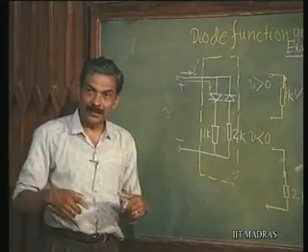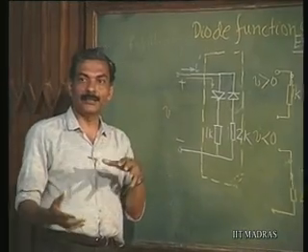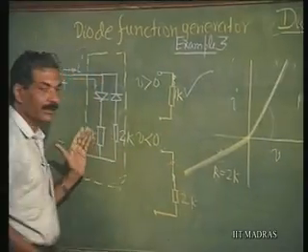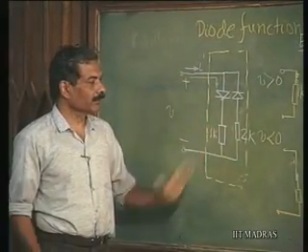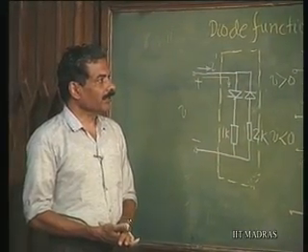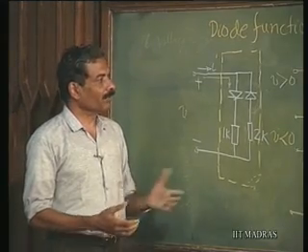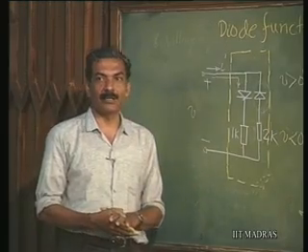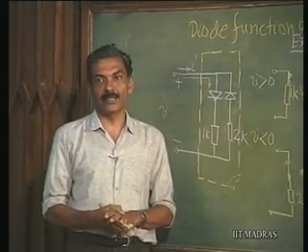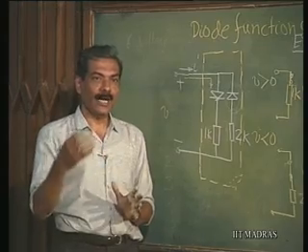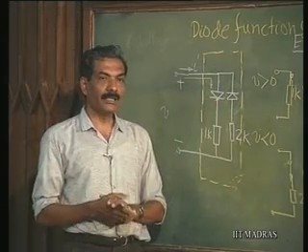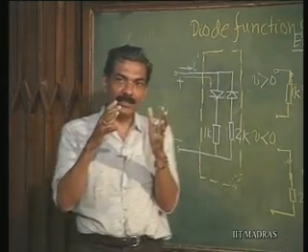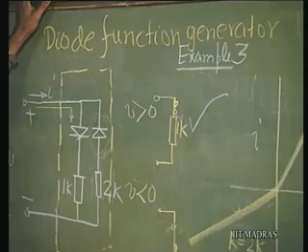So, the basis of this is very simple. You bring in a diode with the series resistance at the required region you want. Therefore, the slope keeps on changing depending upon the resistance you bring in. So, in the next class we will see more about this diode function generation. A special application of diode function generation obviously is a rectifier diode, where we have similar nonlinear characteristics obtained for processing a specific signal which is called sinusoid.